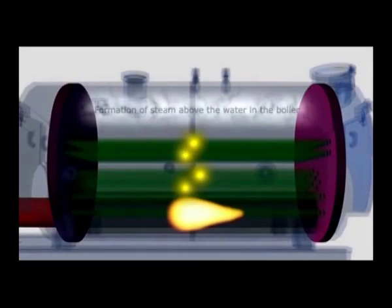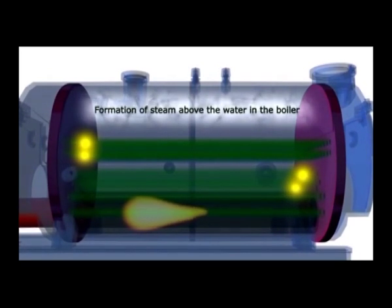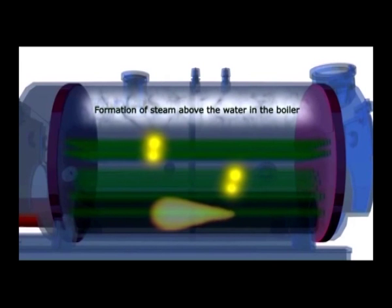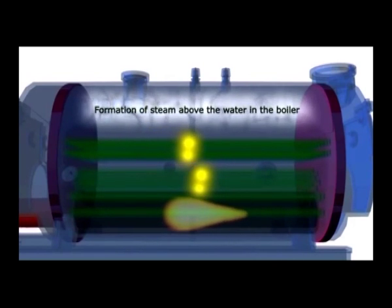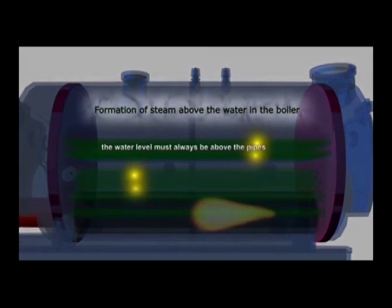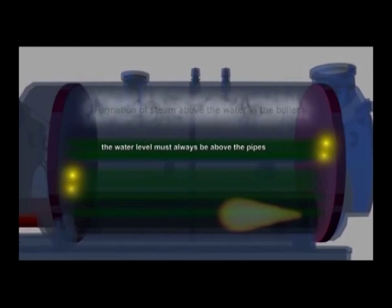A fire tube boiler, on the other hand, is one where the flue gases obtained by burning the fuel are passed through the tubes. Soft water covers these tubes. Any type of material can be used, essentially solid fuel, but it can be adapted to liquid as well as gaseous fuels.